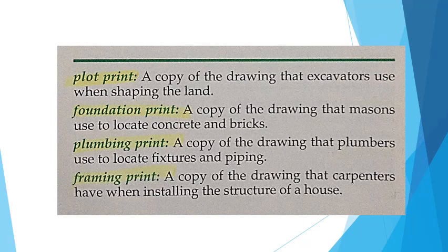In situations where service cables may have to pass through a poured concrete block or wall, the foundation print will show the mason and the electrician where this will occur. A length of conduit can then be placed in the concrete wall before they pour to create the hole.